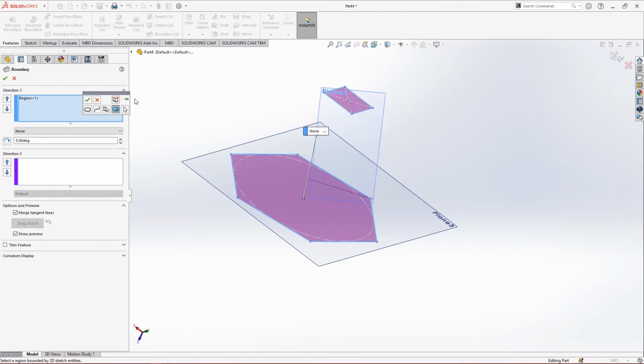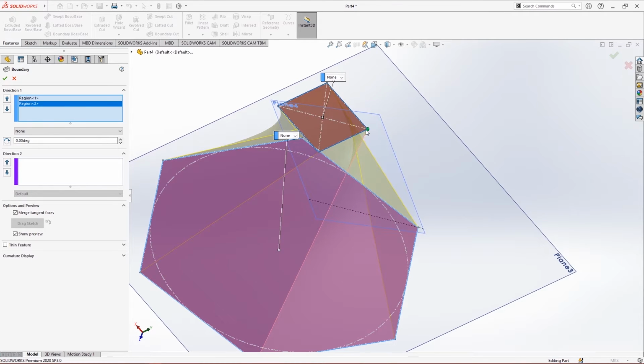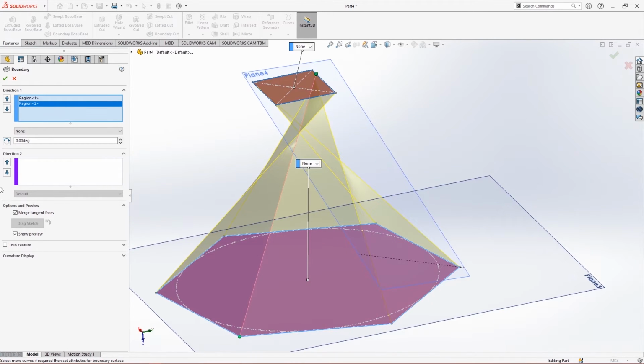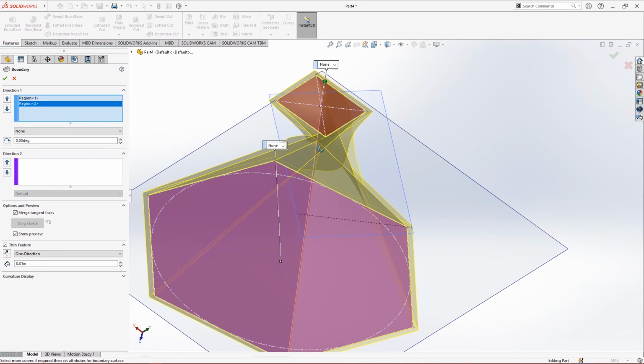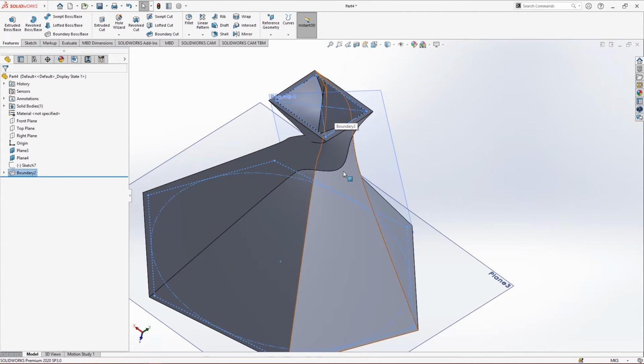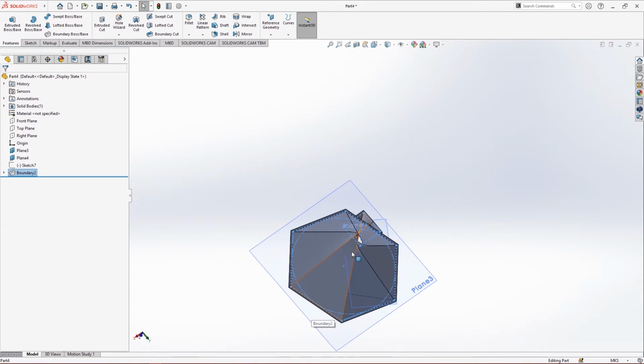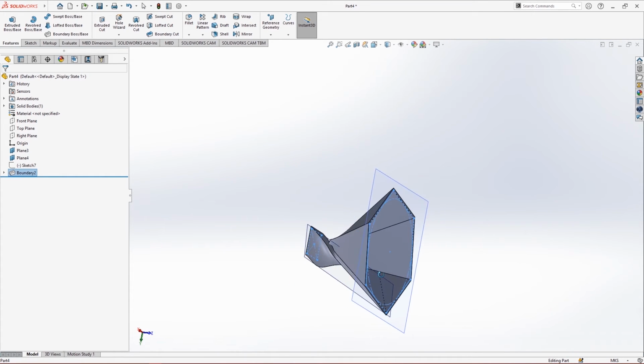Okay, both of these are selected. Right now let me just change some pivot values. It looks much better. I mean, yeah, it looks cool. Now let's just apply the thin feature, and you will see that a thickness will be applied to it. You just click on it and you can select the thickness from here, and just click on it and wait. Now you can see it's a hollow structure, but it looks really cool, right?